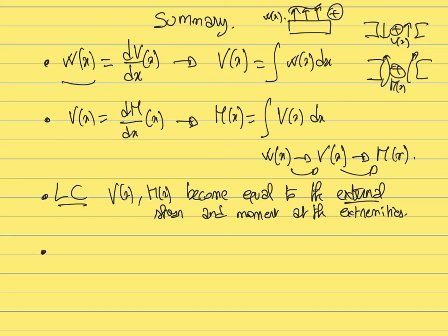And another case that can also be useful are the other equations that we saw when there is a concentrated force or concentrated moment. Again, those are going to be some conditions that can allow you to calculate the value of the integration constant. The first thing that we saw is that if there is a concentrated shear force at a given point, that is going to induce a discontinuity in the internal shear, and if there is a concentrated moment at a given point, then that's going to give you also a discontinuity in the moment.